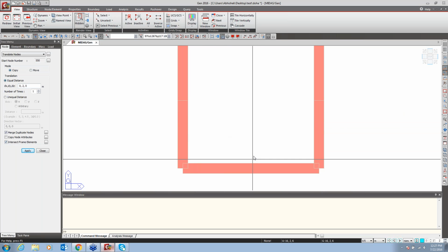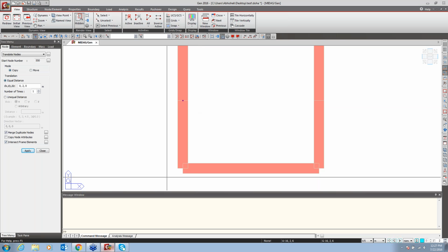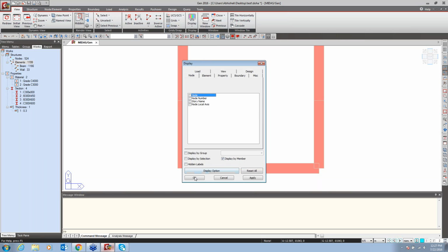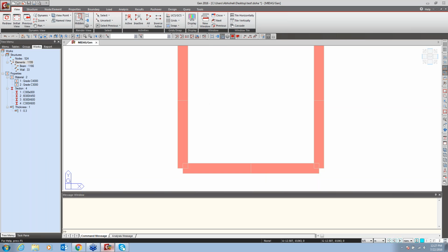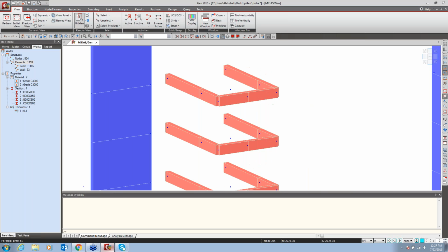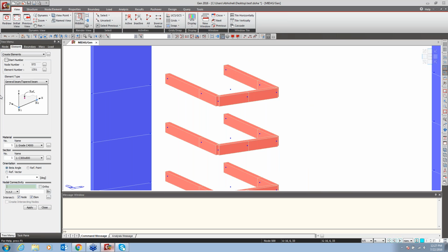Okay, so here I wanted the E-shape shear wall. So we can generate the E-shape shear wall, that I'm just going to show you. Just click these two boxes, X is 0, apply. Okay, now you can see here I just generated one more thing. Just generate one beam, so it will help us in the generation of the shear wall. Any grade is okay.